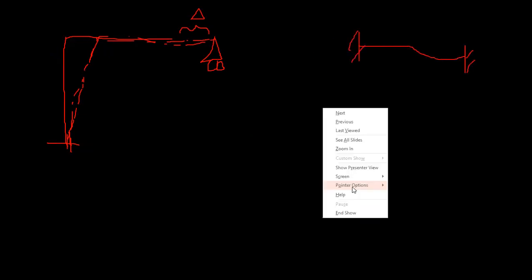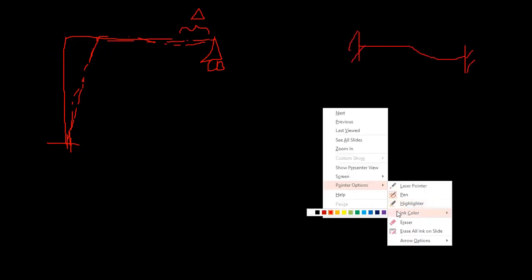This is your final frame, so that has gone delta. This is just a rigid body motion, so this is going to have some fixed end moment due to these laterals.